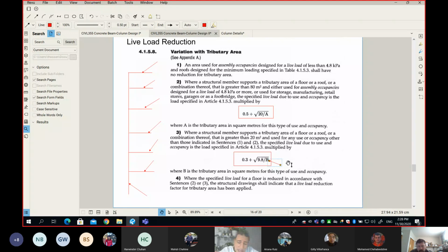0.87. And what does it mean? Look at it, the number is getting less than 1. It means we're starting to reduce. So that's the answer right now. The live load reduction concept is applicable to any structural element: beams, columns, slabs, footings, anything. And it applies only to live load.